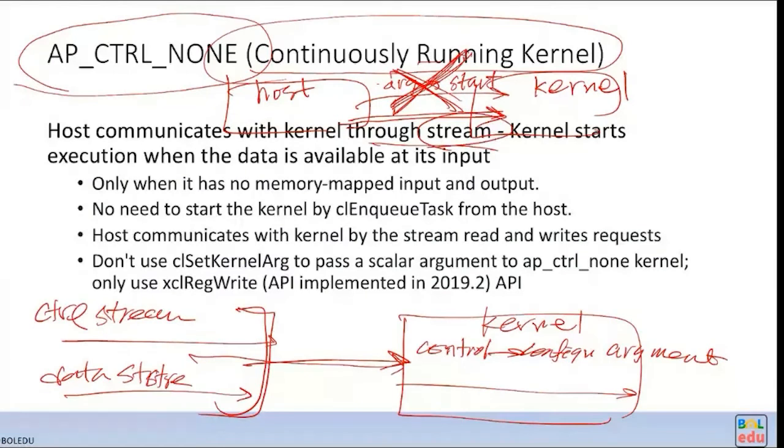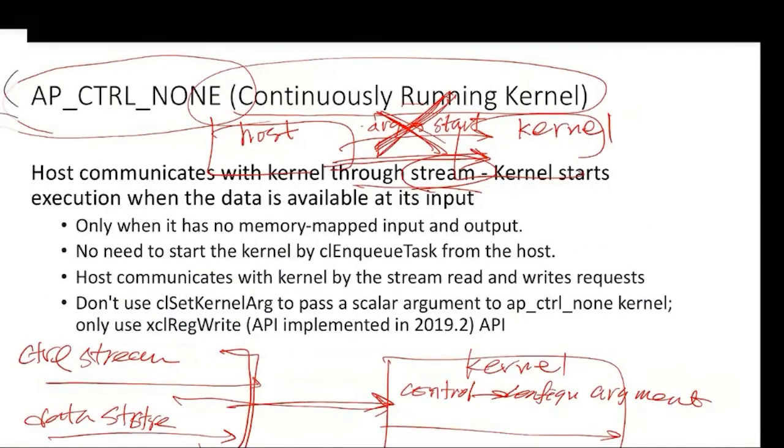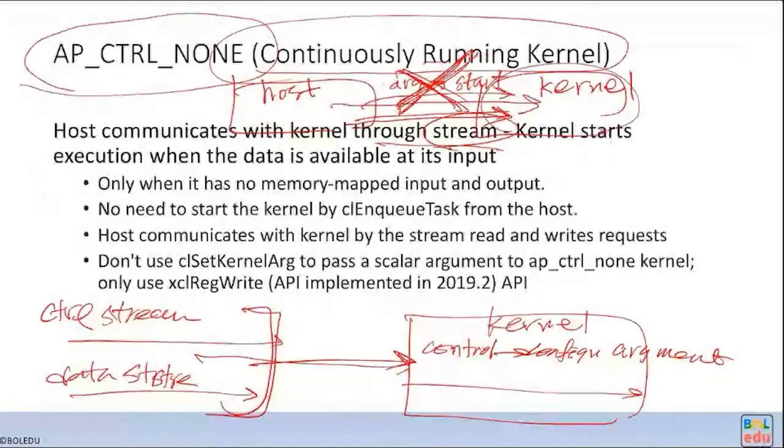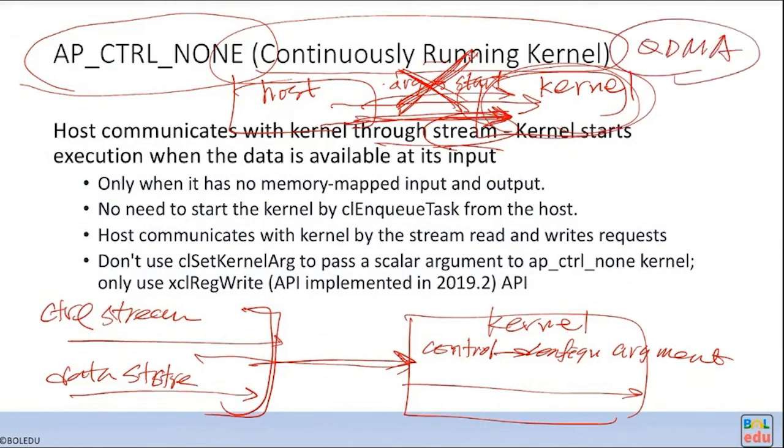So far, right now, we only see the stream from the kernel to host memory, using the DMA IP to transfer data, and then it becomes the stream interface to the kernel function. We have not seen the host simply write the data as a stream to the kernel, even though that's very efficient. Why do we not see that? Because it needs another DMA IP, the QDMA, and I think they haven't pulled it into their package yet.